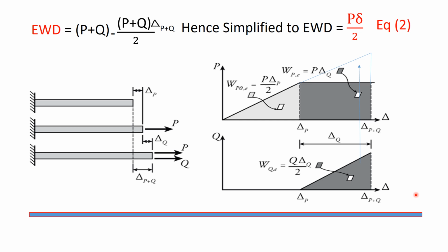The original force P continues to do work as the bar is deformed, even though the force P has not changed, and even though it is not causing the change in the deformation. The amount of work done by P in this situation, as Q is gradually applied, is not the same as it would have been if it was P that causes the new deformation.